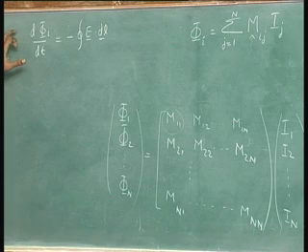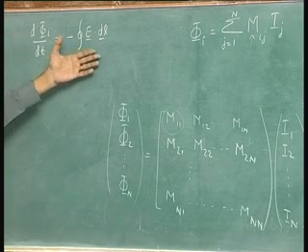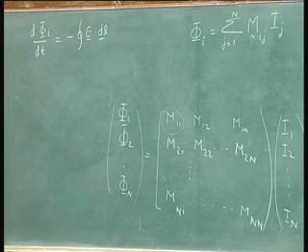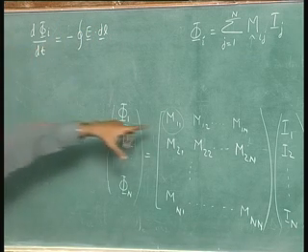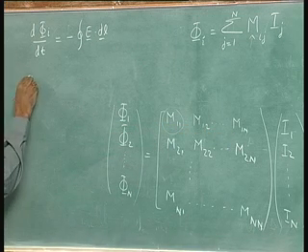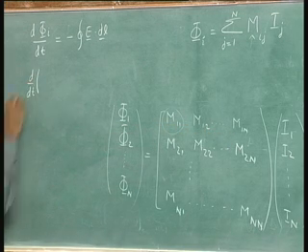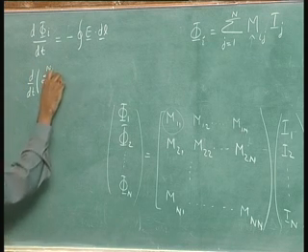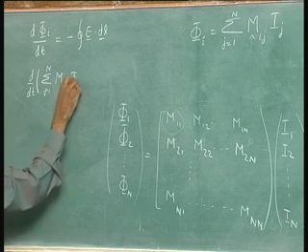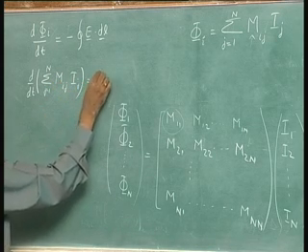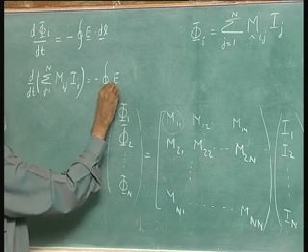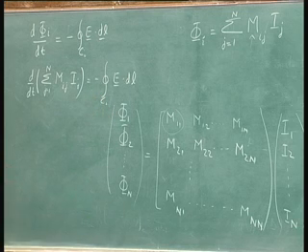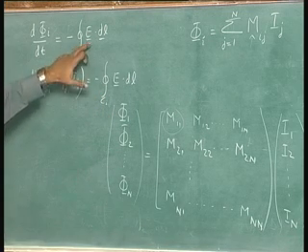Curl of E is equal to minus del B del t, integrate over the surface, you get loop integral E dot dl is equal to minus d phi dt. But phi_i has a representation, so you can say d dt of sum on j equals 1 to capital N of M_ij I_j is equal to minus loop integral E dot dl on loop C_i. So, on the ith loop you have to do this loop integral.